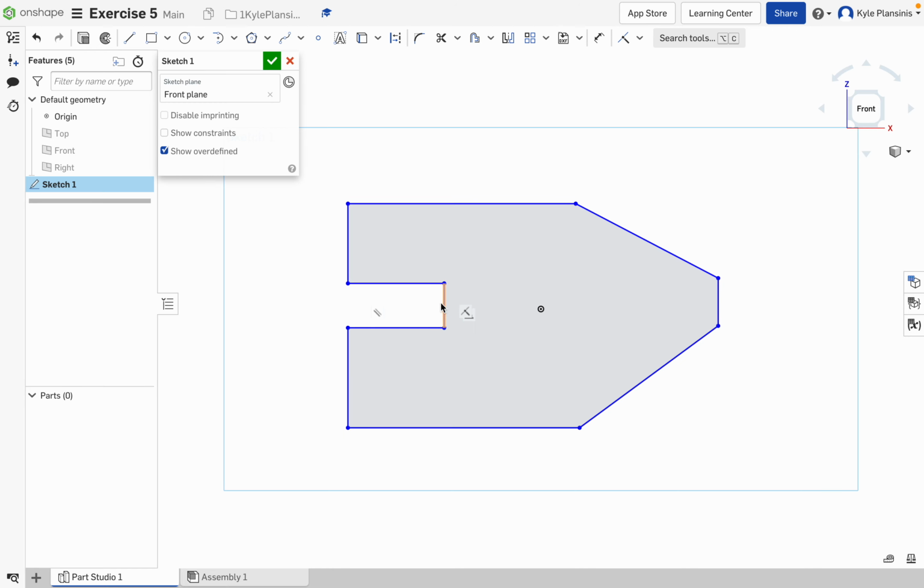One thing that is a little difficult is adding in tangent circles. So I like to just draw them as straight lines where they're supposed to be, and then go back and put them in later. So hitting escape to clear our line tool, we're going to select the two lines that we want to delete. And you could draw this as a circle and all this other stuff, but I find this is just the fastest, easiest method. And we're going to use the tangent arc. We're going to create two tangent arcs where they're supposed to be.